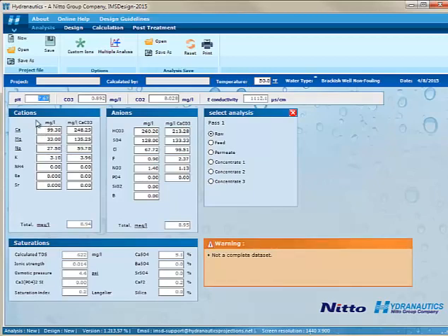And so I've entered all the values into the cations and anions. Notice they can convert it automatically from milligrams per liter to milligrams per liter as CaCO3. That's there. And then if you want to balance the data set, I would definitely focus on either chloride, sulfate, something else that's in this anion list to get it balanced. And you'll see a warning. You don't see the warning here, but you will see one. And you just click on the parameter and it will auto balance it.